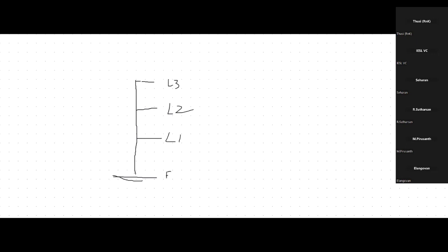What I explained so far is that I make this one a pin. That means there's no moment transfer between column and foundation. But this is a continuous column, with continuous joints, so it can transfer moment. I expect this column to behave like this. If you look at the bending moment diagram, it is supposed to be like this. So I expect the behavior to be something like this.